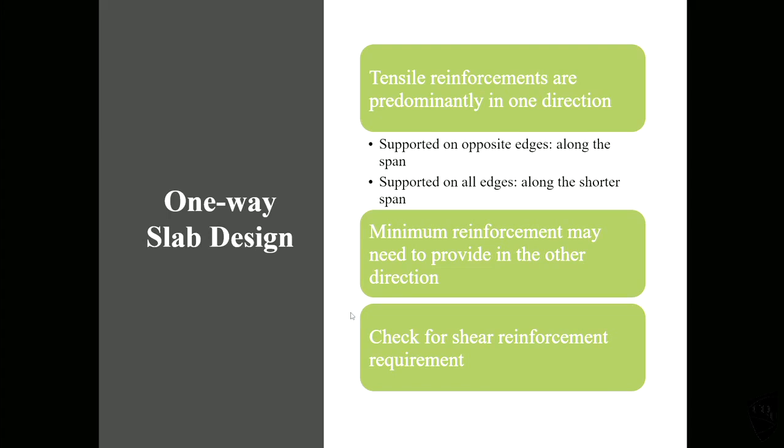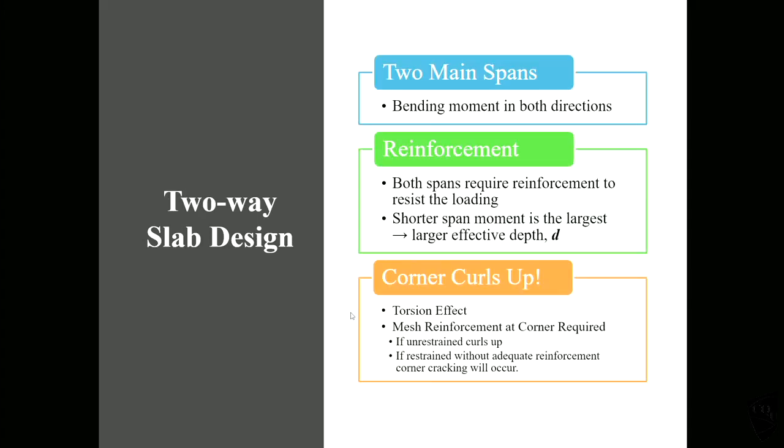We need to do the shear check design requirement, but everyone knows the shear reinforcements are not required. But please check that in the assignment. For two-way slabs, you need to do for both directions.